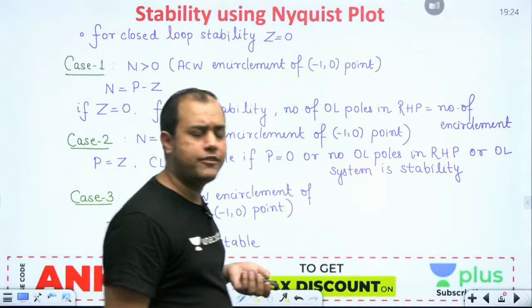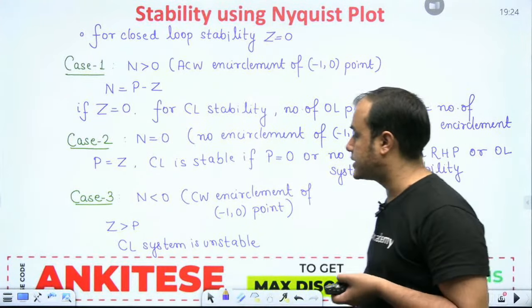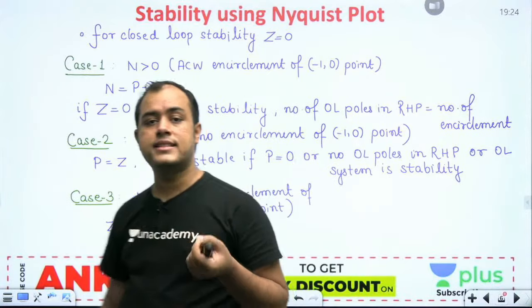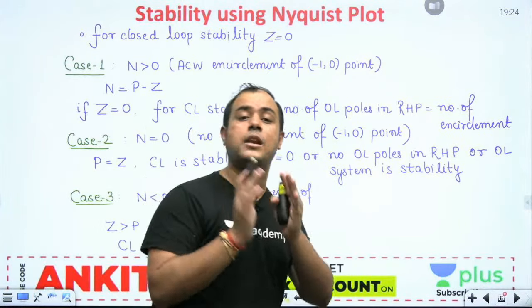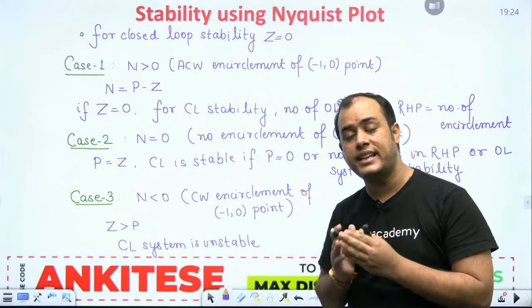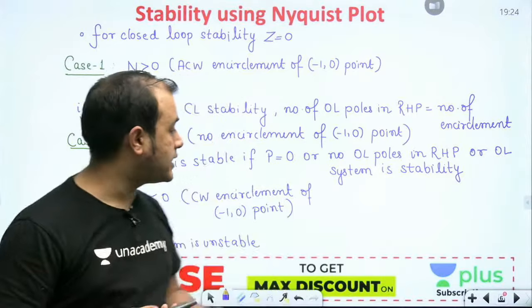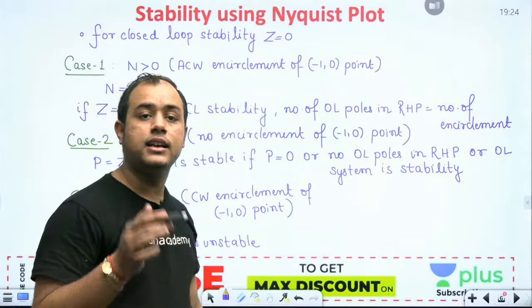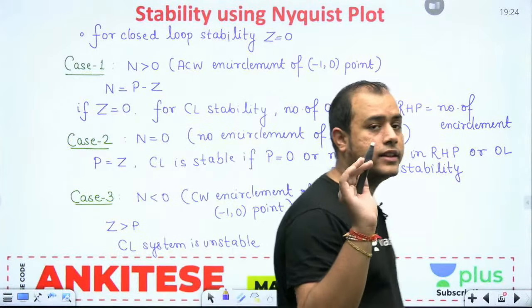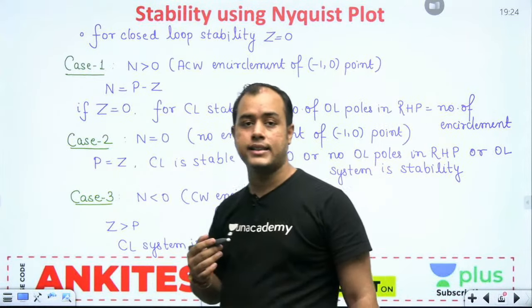Vibhud, I have drawn only one type of polar plot for a type 1 order 3 system. The only difference in the two polar plots is their real part. So based on the transfer function, you will have to check the real part at omega equal to 0 so that you get to know where the curve is starting. One curve is totally near the imaginary axis, which means its real part is 0.